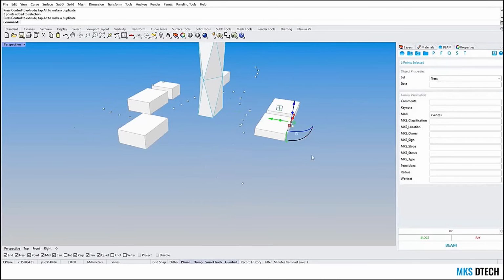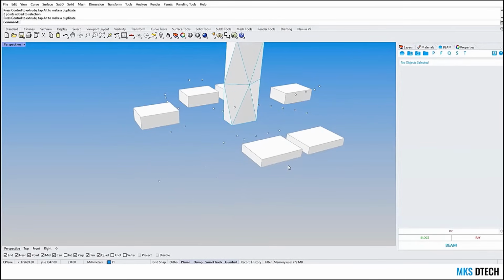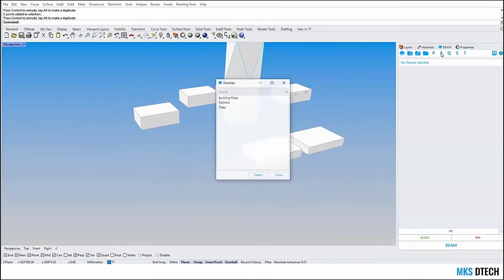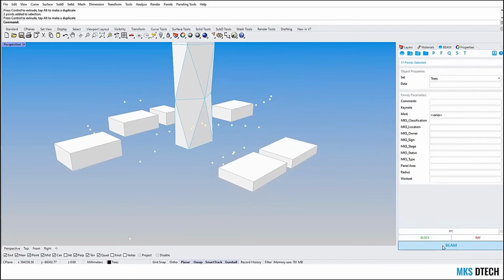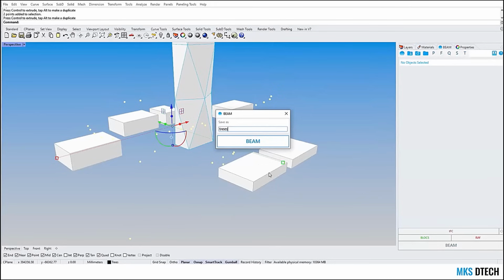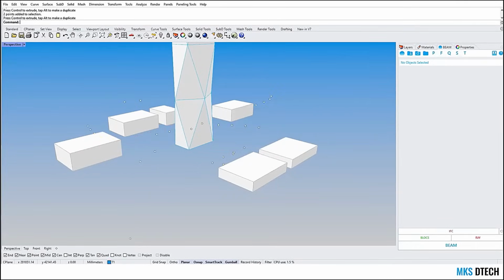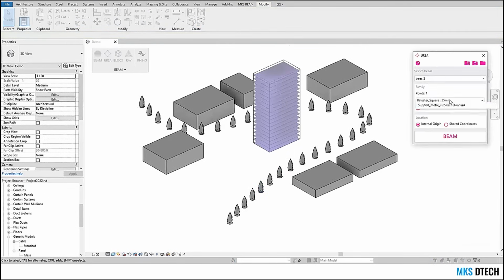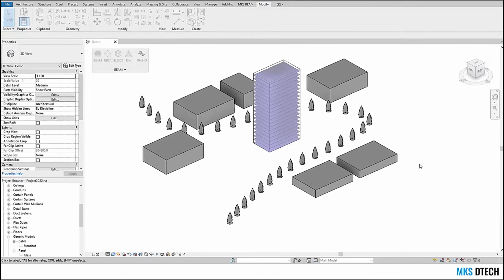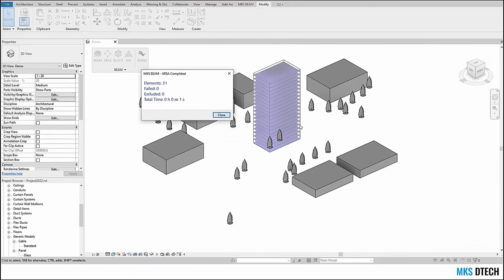Maybe this is nice if, I don't know, you have a Grasshopper script to move this, to create something interesting, or you simply want to move this tree somewhere else. We go back to the RF tool, we select the trees, and then we can just update them, calling them trees 2. Now let's go into Revit with the usual Ursa. I'm going to search for the tree, and I'm just going to update them. So I don't have to delete them, I can just update them.